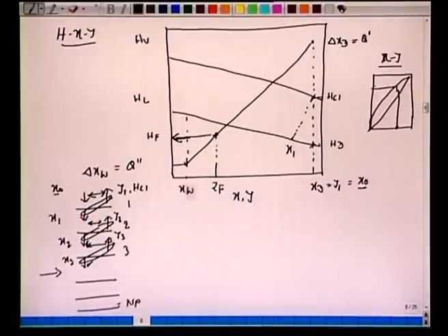Okay, so this is Y1, we will get X1 here. Knowing this Y1, we read from this graph as X1, we obtain this X1. So this will correspond to stage 1. Look at this stage 1. Vapor leaving is in equilibrium with this liquid. We have X0 same as this Y1. So first one, reflux concentration is same as the vapor which was leaving the top plate. It's a total condensate.